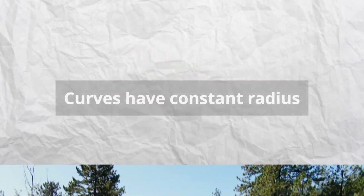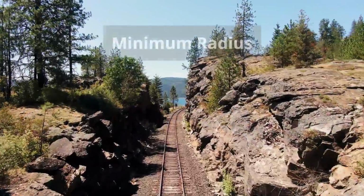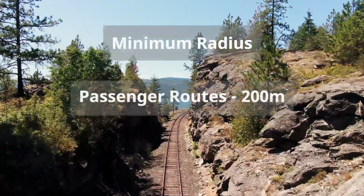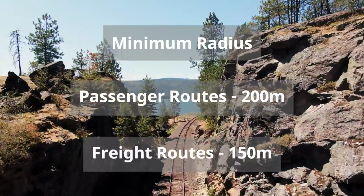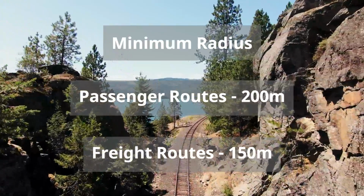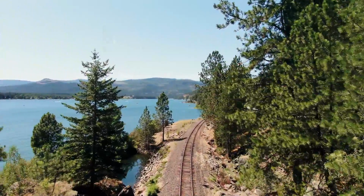Curves in track have a constant radius. The radius can be as low as 200 meters for passenger trains, or 150 meters for freight routes. In exceptional circumstances, it can be as low as 125 meters. Curves will normally have a constant cant applied to them.